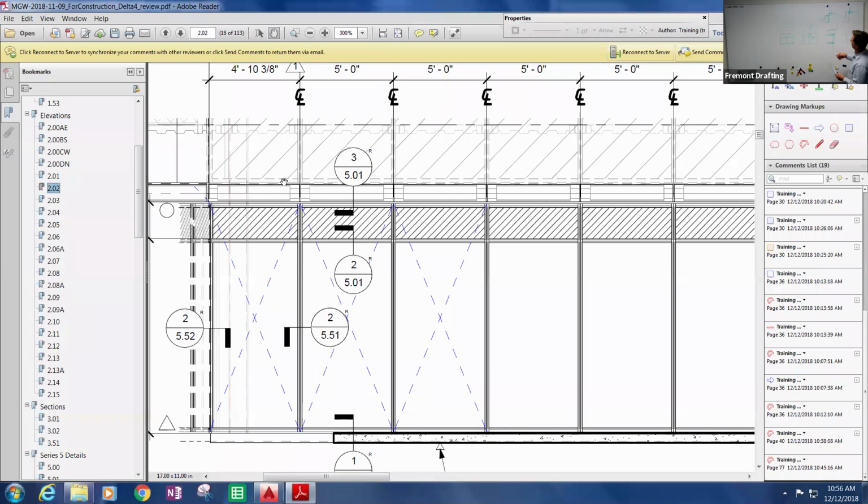And then when you have seismic moving the other direction, this panel that's translating this way is just leaning out, same as our windows are leaning out. So there's no issue coming this direction. It's in this plane here. And so that caulk joint size becomes what we engineer to stretch and not tear with the amount of movement.